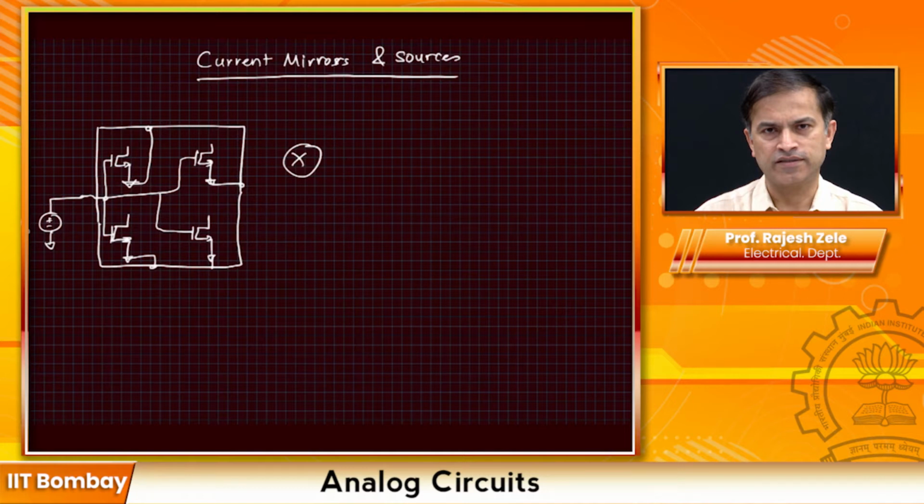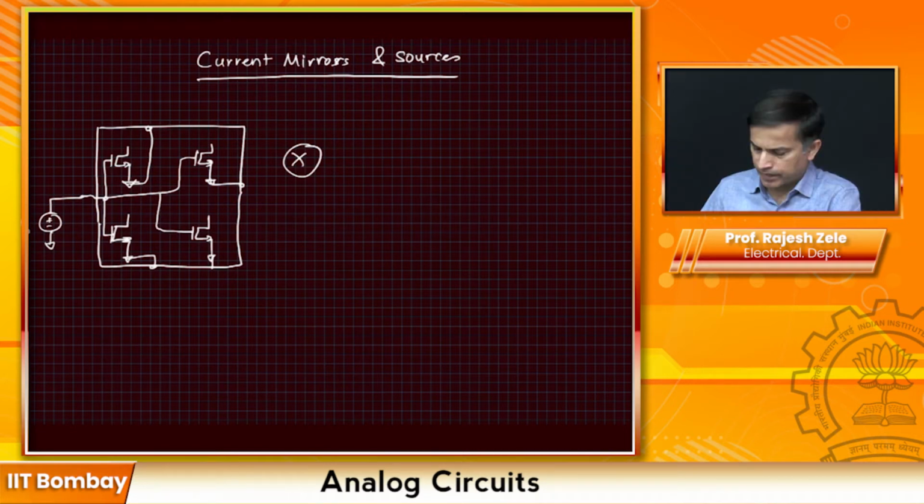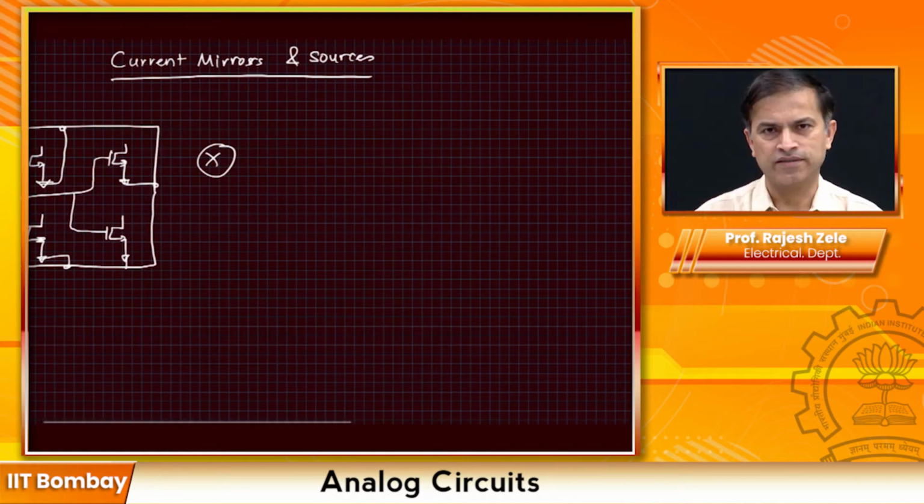So how do you do that? I'm going to show you what we do on most of our chips, especially in production-level operation. You can get by with the configuration shown maybe in the lab and tweak each voltage source, but if you have 1000 transistors, it gets totally out of hand. With maybe 4 or 5 transistors you could probably tweak each voltage, but it is definitely not recommended.